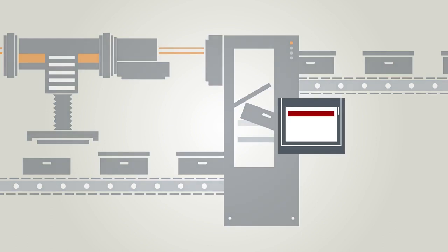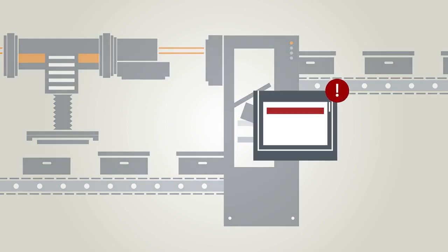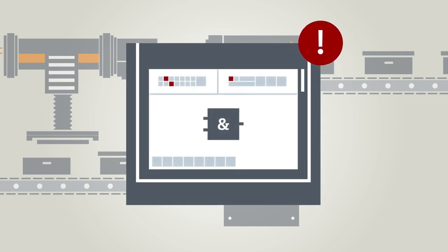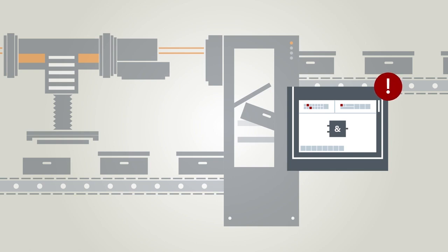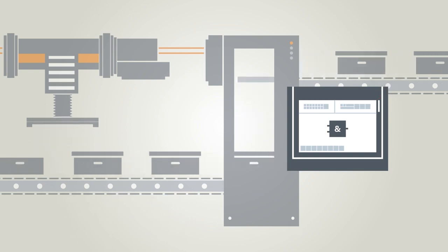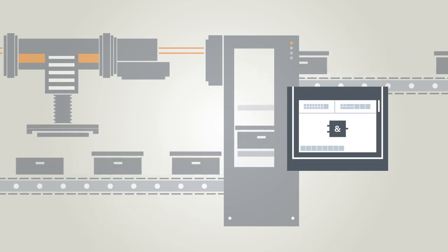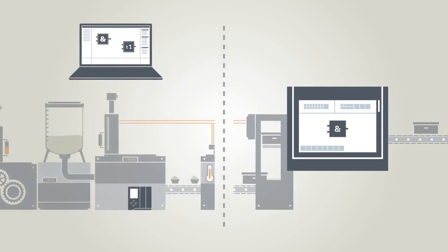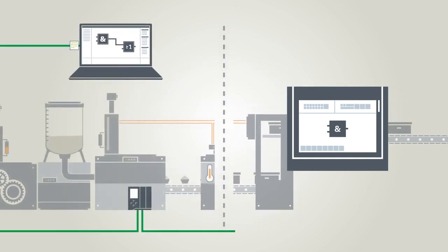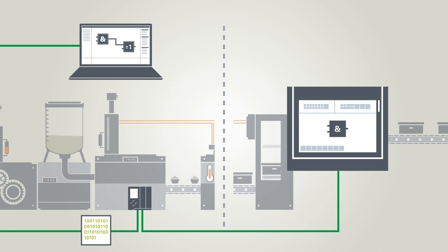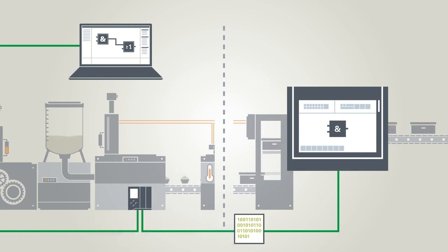You can perform the diagnostics directly on the operating device with preset objects for this purpose. As a result, all faults can be detected and remedied even without a programming device. Even program changes on the controller can be detected by the operating device, without having to reload the operating device.